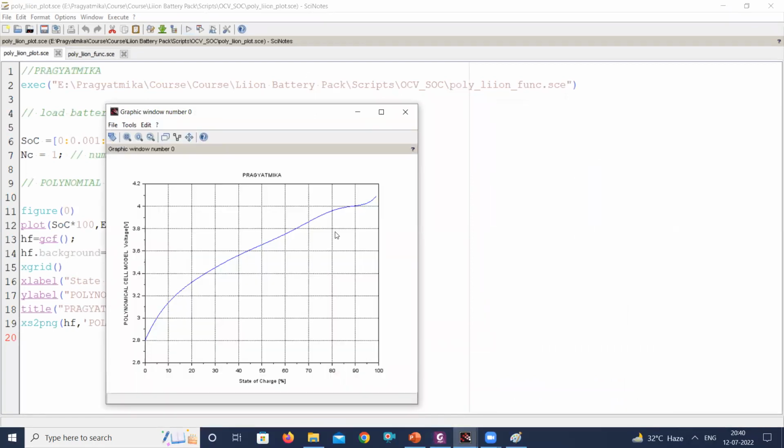Okay. And how accurate this is to our physical values, that's what the calculations and the predictions versus the real values differ. Based on that, you are also calculating the standard deviation of the differences. That standard deviation is through your RMSE, and the genetic algorithm gives you the values to fit the curves. You will be multiplying the SOC value at multiple points, represented here as K0, K1, K2. That is called the coefficient of your curve, and we are getting the coefficients through the genetic algorithm.